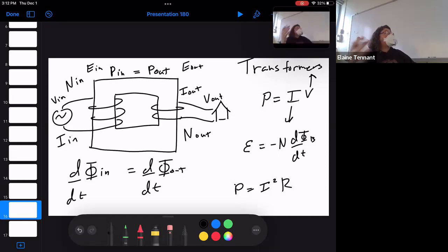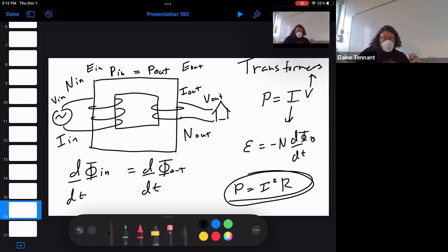And potential difference is nice, right? Because nothing has to move for a potential difference. Like I have a capacitor, nothing's moving, it just has a potential difference. So you don't have to worry about that high resistance because you're not running a current through your wire. You're just making a potential difference appear, which means that this power coming into your city is coming in at a very high voltage and very low current.